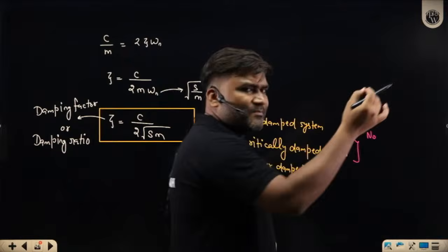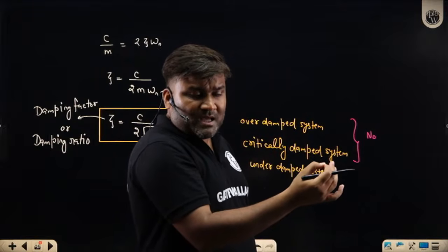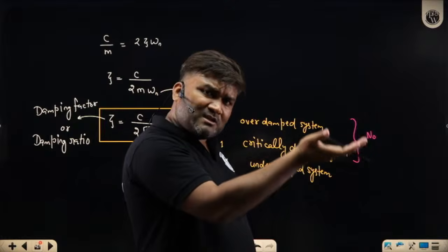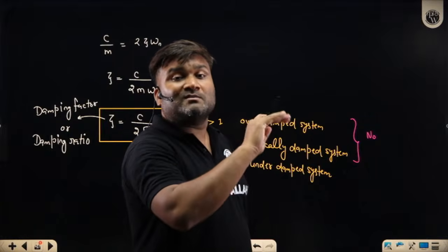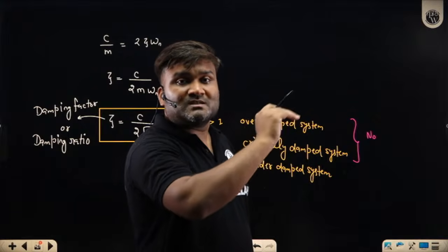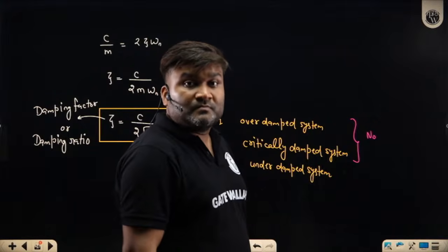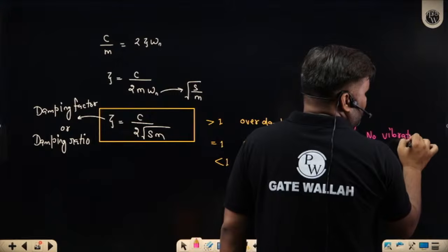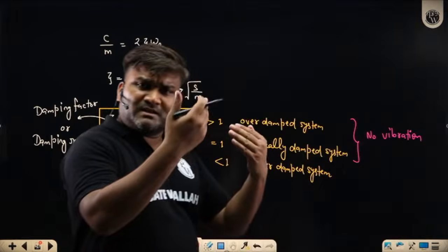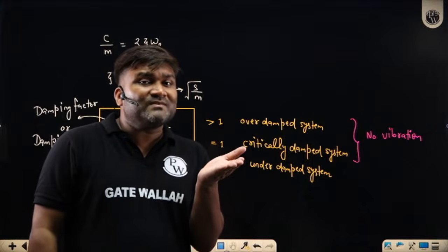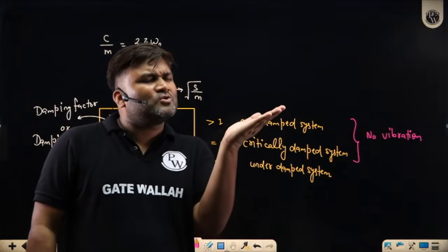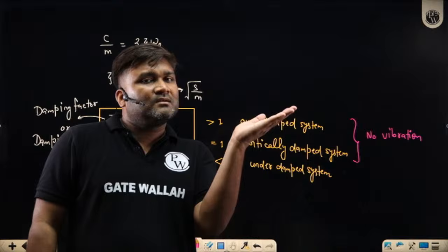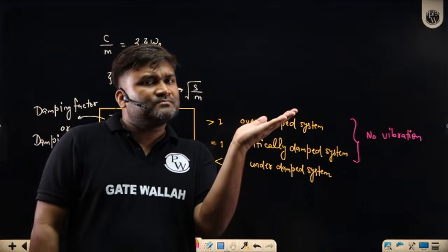And if friction is very, very high, overdamped or critically damped, there is no vibration in the system. You have disturbed the system from the mean, you have taken it somewhere, released it. System slowly goes back to the mean, and in this motion only, entire energy is lost. System's entire energy is gone. System will come to rest because friction is too high. It will not show any vibration. Keep on increasing the friction, the system becomes even slower. System slowly goes to the mean, and upon reaching the mean position, it stays over there. No motion further. That's it. All energy is gone.